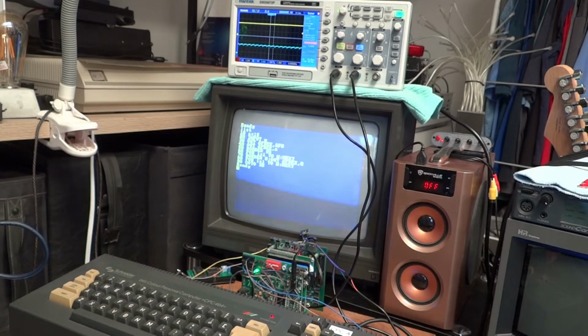assuming that both the LED and the screen colors have been changed at the same time, or with a microsecond delay, depending on the kind of program or whether it's BASIC or machine code. There will be some lag between those two operations, but the time that you are measuring between those two events in the video footage should then be the lag introduced by the Scart to HDMI or RGB to HDMI converter, right?